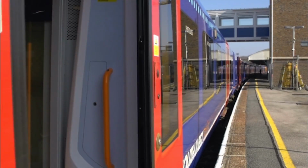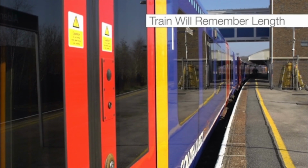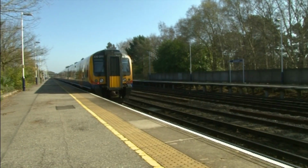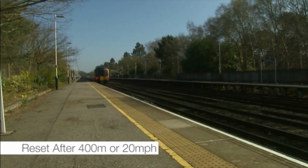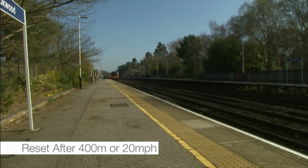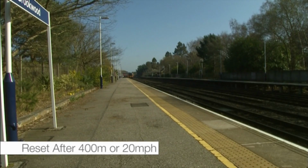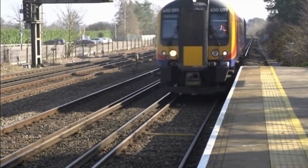If the doors are closed and then re-released, the train will remember the length of the platform and how many doors should be opened. The system will only reset itself once the train has moved 400 metres or achieved 20 miles per hour. There is no facility to manually reset the system. The train will then need to go over the beacon for the next station before it knows the next platform length.